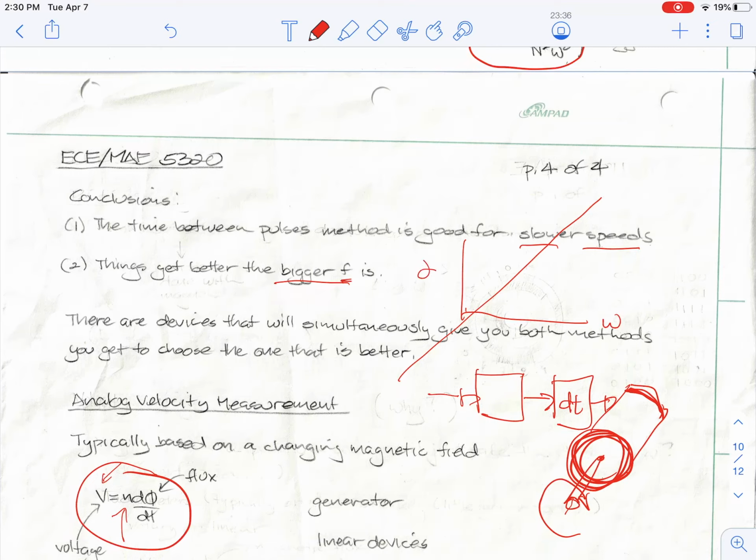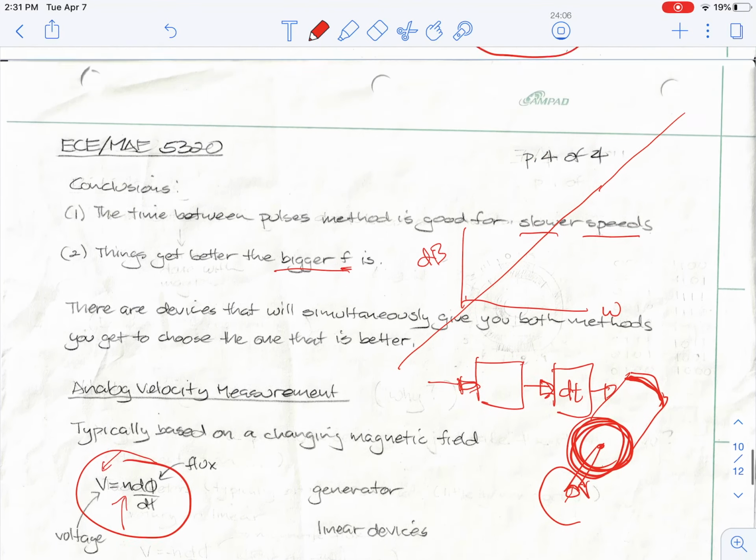And so this is omega, and this is dB gain. And as I go higher and higher in frequency, the value gets bigger and bigger. And so any noise that occurs in an environment will be amplified by differentiation. So as you're measuring something in position, you will amplify every change, and it will get bigger and bigger and bigger. And any measurement noise that happens to occur will be amplified by the differentiation procedure.